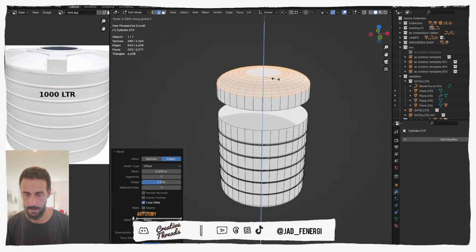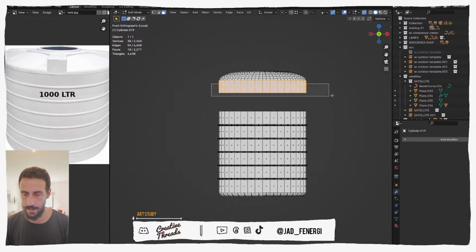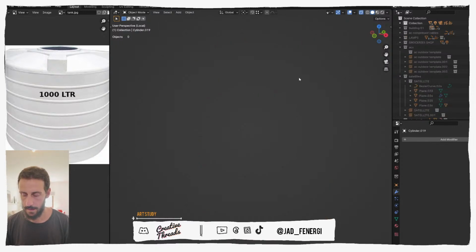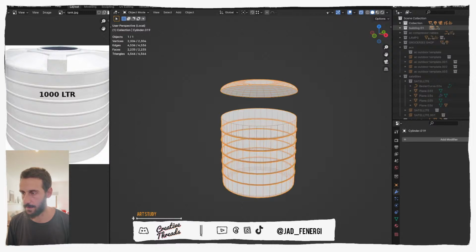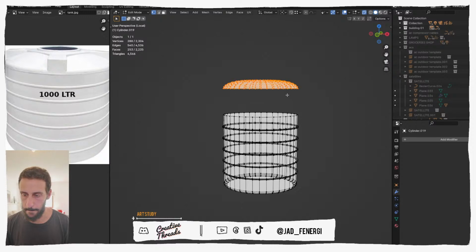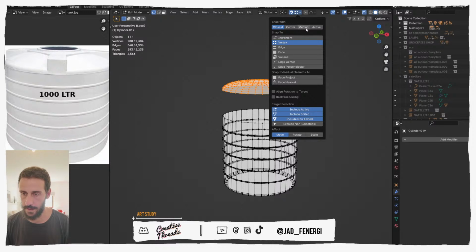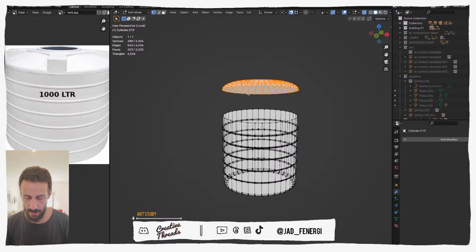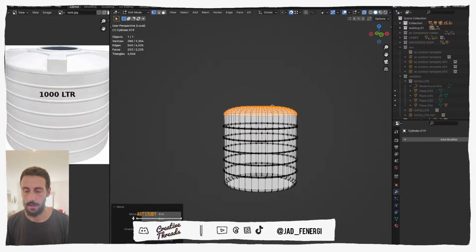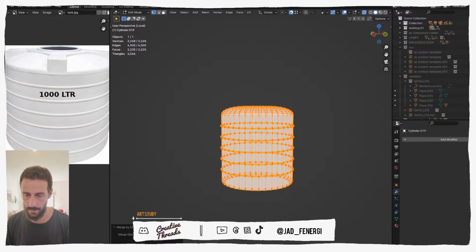Something like this. Yeah, that's good. Let's pick all of these faces and let's delete them. Then I pressed on the view layers, which is always a bad idea. Then we're gonna just try to snap it. So turn on snapping, its vertices, the closest, we'll see what will happen. G, C, that's it. Now we can select everything, press M by distance. That should have done the job.